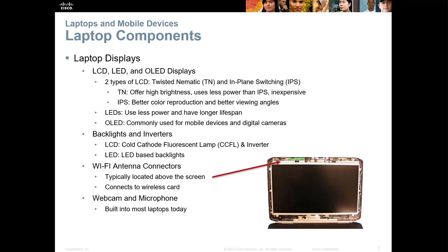On many laptops, a small pin on the laptop cover contacts a switch when the case is closed, called a cutoff switch. The cutoff switch helps to conserve power by turning off the display. If the switch breaks or is dirty, the display remains dark while the laptop is open. Carefully clean this switch to restore normal operation.